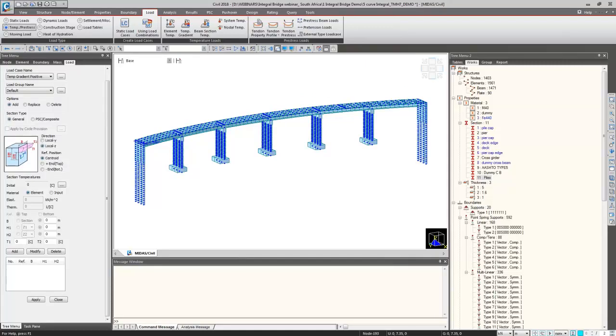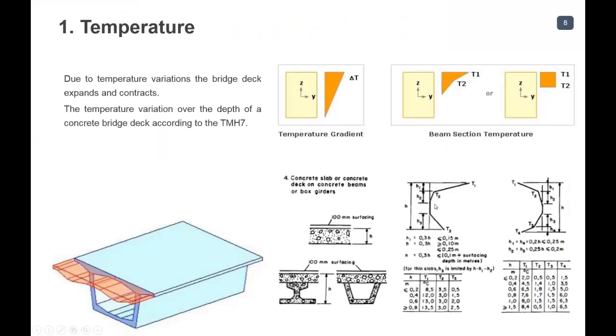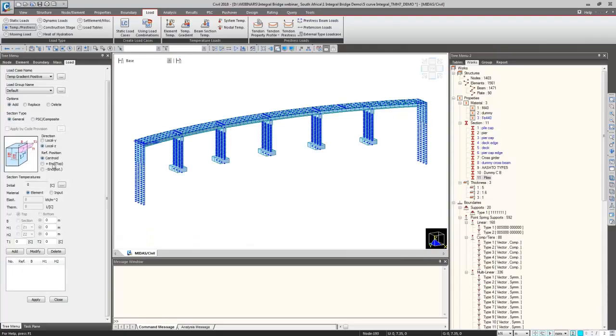So as you know, we need to apply this nonlinear temperature gradient across the girder. So I'll just select this end top as reference. So at the top, the temperature is, so let's go to PSC here, the section type PSC or composite, where the B would be automatically calculated. So I'll select the width to be section. The program will calculate the B automatically.